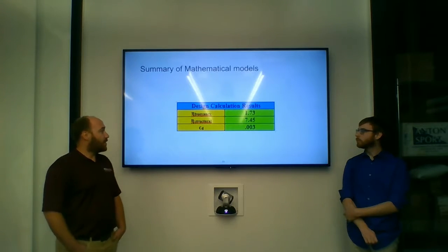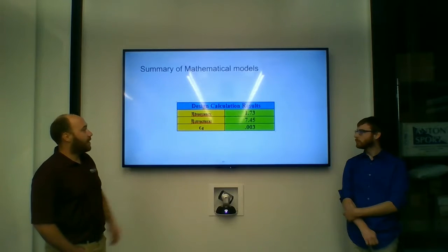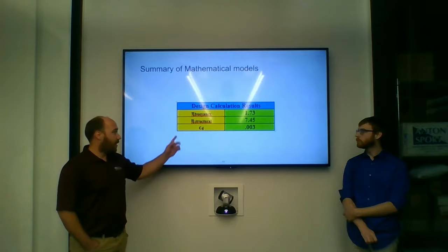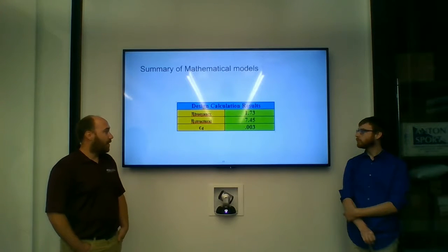And then just to summarize our calculations, we have the same factor of safety for the buoyancy of 1.73. We have a factor of safety on the structural frame of 7.45, which is sufficient, and then a very low coefficient of drag.